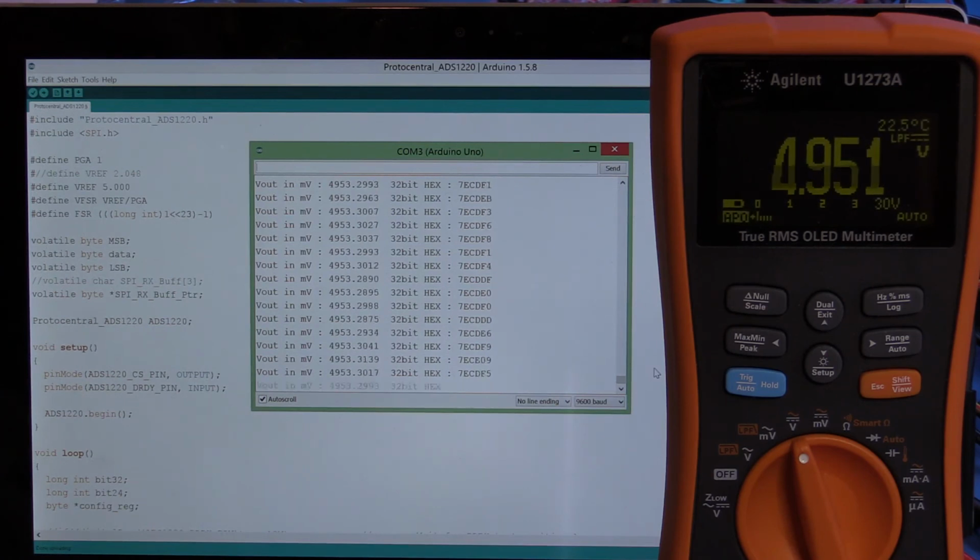So with the digital to analog converters that are able to go from 0 to 5 volts coupled with the analog to digital converter now that can read 0 to 5 volts, the next step would be to add the power stage to this that we were looking at in the previous video, and make it a complete computer controlled system. So I think that pretty much covers everything that I wanted to show in this video. Just trying to think if there's anything else. I don't think there is.